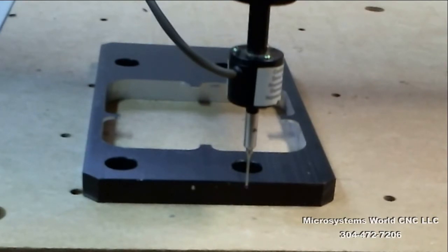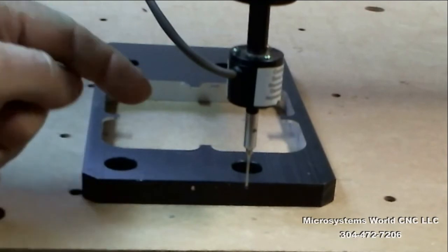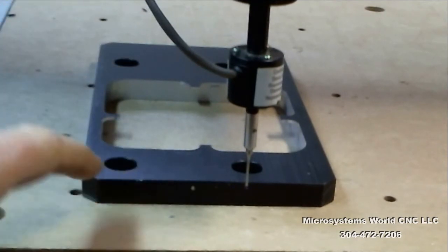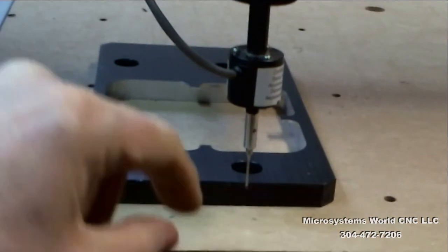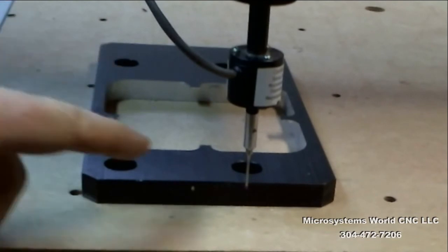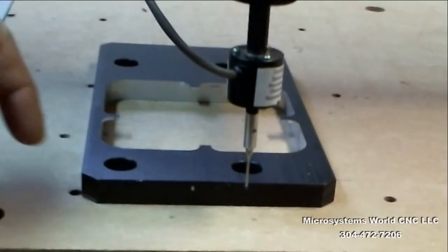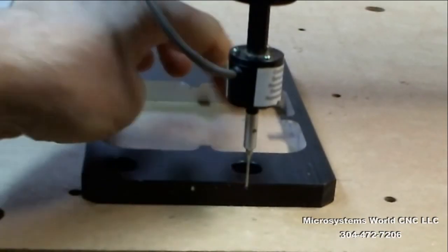Hi, this is Mike Queen from WinCNC, and I'm going to do an outline scan or edge scan on this piece of material. The outline scan can either start in a positive Y direction or a negative Y direction. It can start its initial move in the X positive direction, which on this piece would force it to go in a counterclockwise motion, or it can go in an X negative direction, which would be a clockwise motion. It will scan all the way around this.